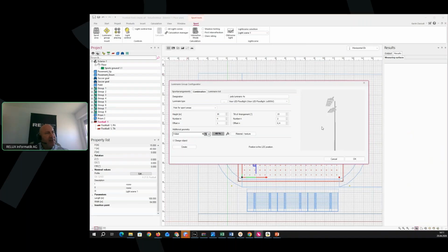And a very nice feature additionally, as you can see here, we have an inclination of the luminaire arrangements on the pole. Here it is 15 degrees, because sometimes the maintenance guy is just climbing up here to the platform and then is just executing maintenance work, and you have a lot of poles which have this inclination of 15 degrees. Otherwise, if we don't have it, you have to arrange everything by hand, and this is, I think, very painful, and just to have it as a pre-setting, you are avoiding a lot of pain, I would say. Okay, let's go back.